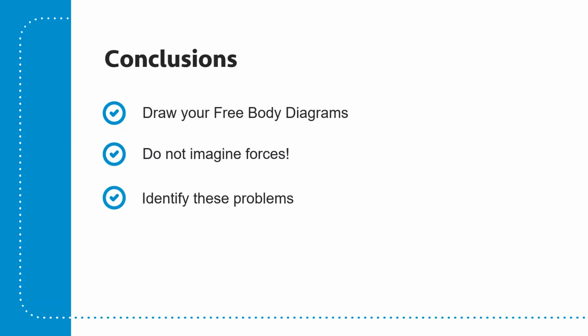Draw your free body diagrams, draw your kinetic diagrams, draw your kinematic diagrams, draw every diagram you can, and don't imagine forces that aren't there. There's a tendency to look at problems like this and desperately want to have a force that you intuitively imagine exists, and it doesn't. Don't do this. Just draw what's there.